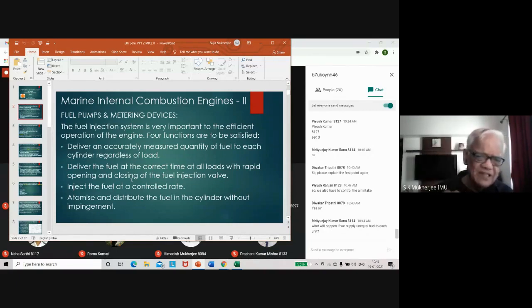So plus or minus 3 to 5% error in the gauges is permissible. Plus, it is not possible that all of them will be exactly the same. It never happens. I will say up to 5 degrees plus or minus is variable in the exhaust gas temperature.